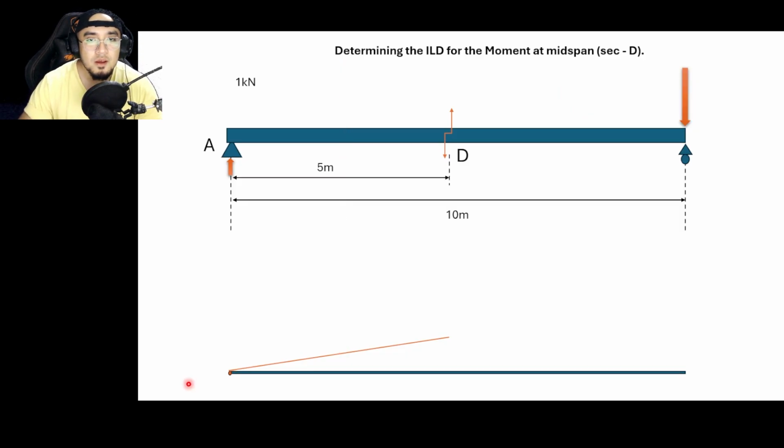Again, using this location, that is 1 kilonewton. Using that location, let us get the moment about this point. In order for us to get the moment about this point, since we are to cut a section here later on, choose the left as the beam that we are considering. Let us first solve for the support reaction at this point.